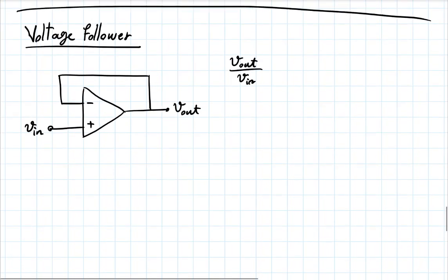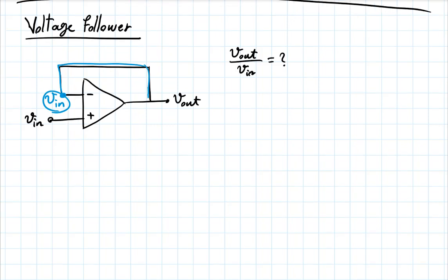Maybe the name of the circuit suggests something to you. Well, let's solve it. If this is Vin, this node will have to be Vin. And, well, that's all the same node. So what's the use of this? I take a voltage and I create the same thing. It's not very creative. Yes.